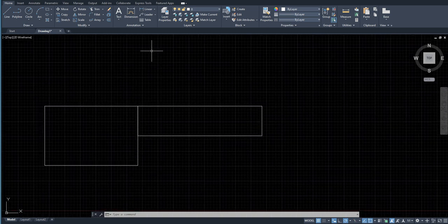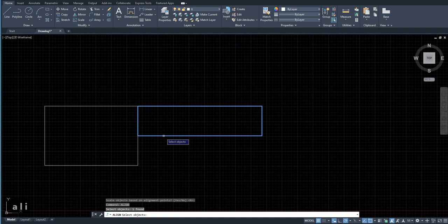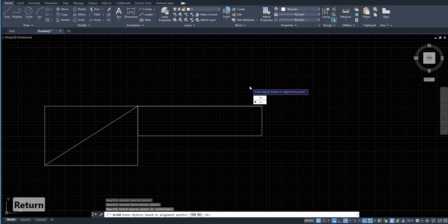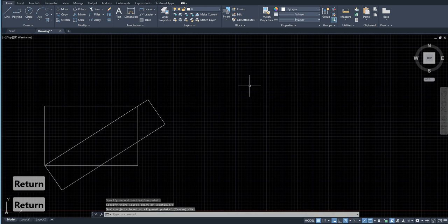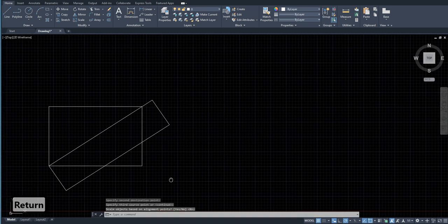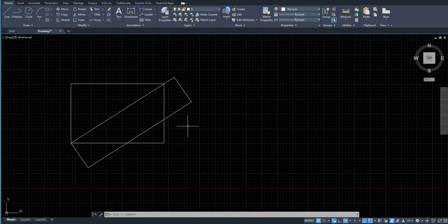Obviously, instead of using the command align, you can just use the command rotate and move, but sometimes that's a pretty lengthy process. For example, if I just want to align my axis, and instead of this point, I'm just going to select these 2 points for now. Let me see what it does, and I press enter. It's asking me whether to scale. I'm going to say no. So it just aligned my object like this. So that's how the align command is used.